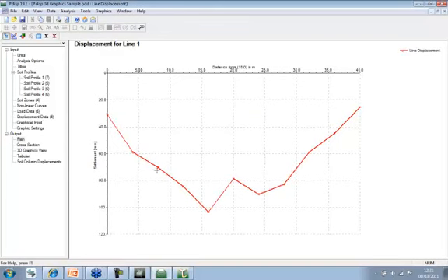And for example, along that line, say I wanted the highest point. As you can see, right on my screen, I'm showing the ordinate here of 102.65. So that's pretty much our maximum displacement. And I know that aligns with 16.1 meters along my specific line. But alternatively, I can go to the tabular output and pick that up.